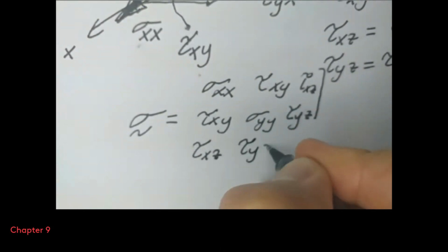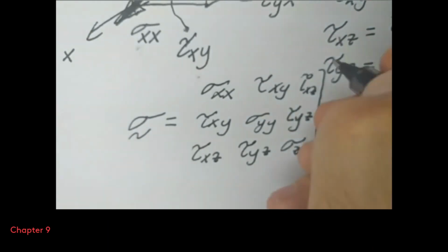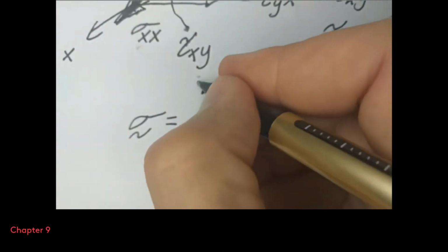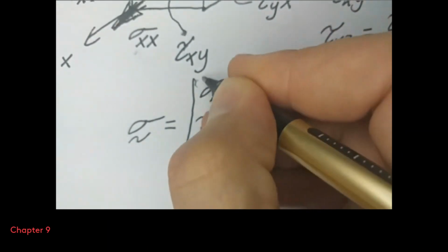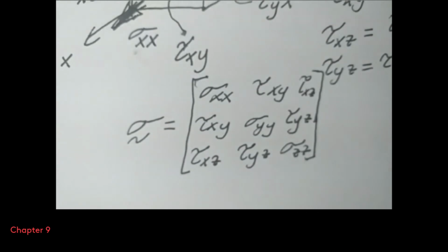So in matrix form, these are our stress values. But the point is, calculating the 3-dimensional state of stress may not be that simple. Let's focus on much simpler problems, which we call plane stress.